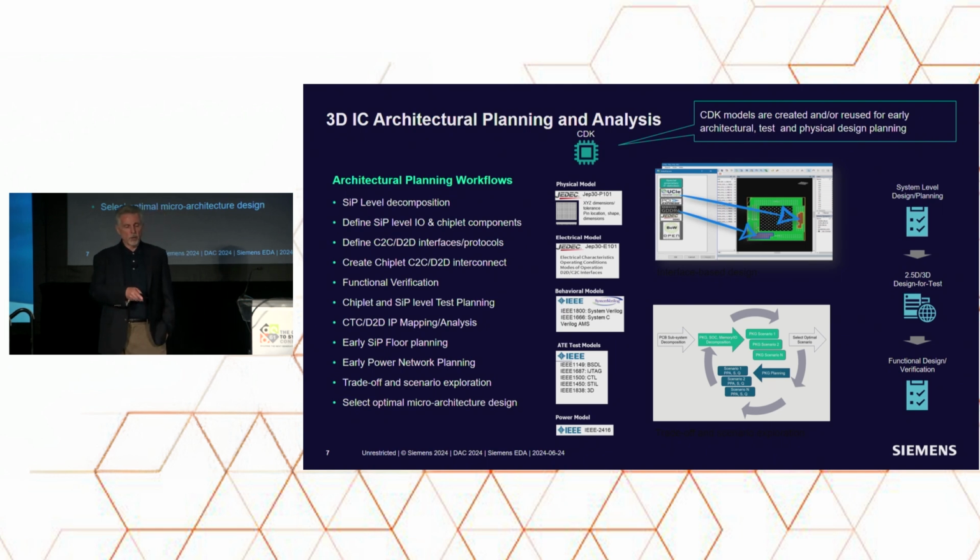An example here, I'm showing interface-based design. So this is leveraging some of that die connectivity that is defined in the actual part model for the chiplet. So you can develop scripts that would actually be able to generate some of the connectivity very efficiently to connect some of those high-speed interfaces, whether it's die-to-die or going outside the chip.